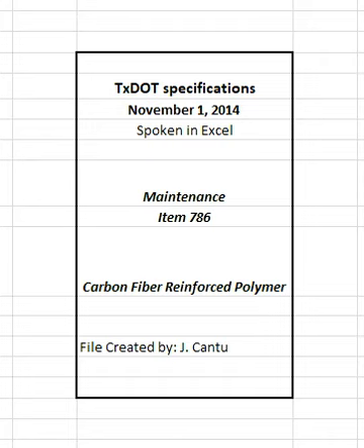5. Payment. The work performed and materials furnished in accordance with this item and measured as provided under measurement will be paid for at the unit price bid for carbon fiber reinforced polymer protection, and carbon fiber reinforced polymer strengthening. This price is full compensation for all materials, labor, equipment, pull-off testing, including repair of test sites, manufacturer's supervision, and related work necessary to prepare the surface of the concrete, to install the CFRP system as detailed on the plans and apply the protective appearance code. When not shown on the plans as a separate pay item, payment for installing CFRP is subsidiary to the pertinent items.